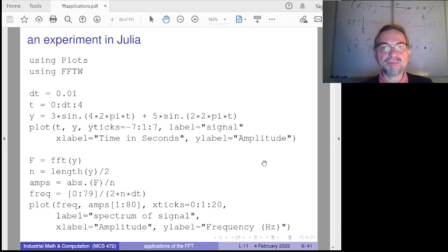So in the time domain, we are going to see big wobbles and small wobbles. That may be an indication that there is some composition going on, so it's not a pure sine function. The nature of the signal will actually become very clear when we go to the frequency domain, when we make the spectral plot.